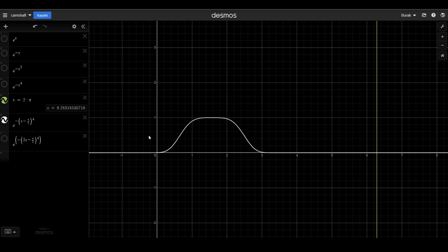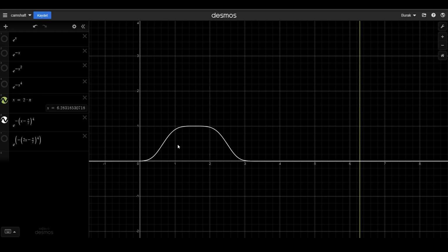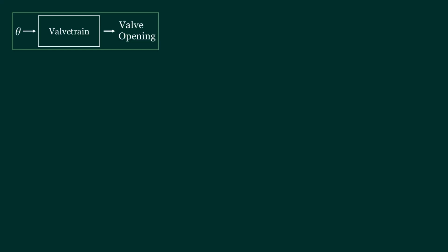Lastly, we know that this cam profile is for a 4-stroke engine, and if we use a 2:1 ratio for the camshaft, the valve should open and close within a quarter of the cycle. We will see that in a minute with the animation. So the signal should shrink to a quarter of the rotation, and here we have it, the equation of a simple cam profile. You can make it more realistic and complex, but it's enough for me as a beginning.